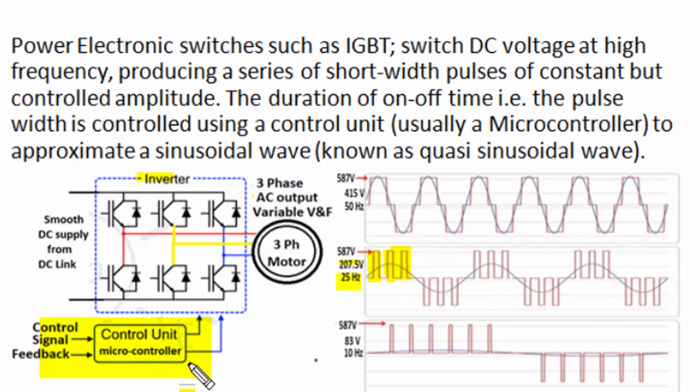This microcontroller unit controls the on and off duration of these pulses and controls positive sequence and negative sequence pulsed output in such a way that the resultant pulse width modulation manages a nearly sinusoidal output wave, and we get a good fundamental frequency component and reduced harmonic component by this PWM technology.